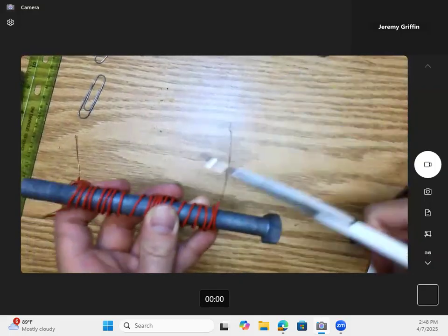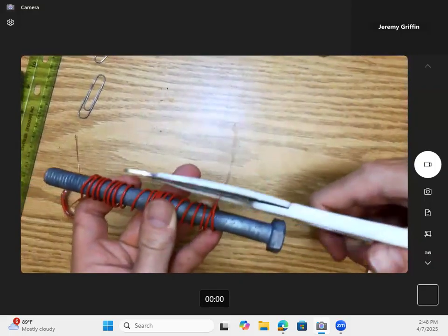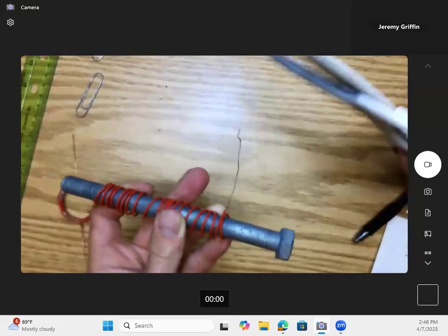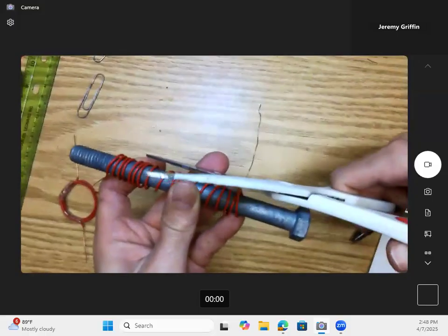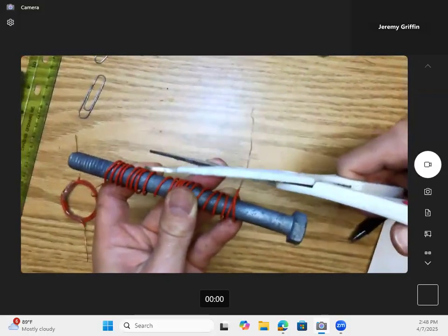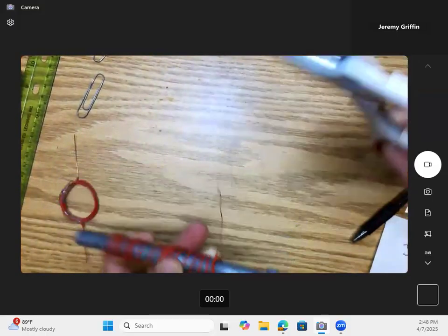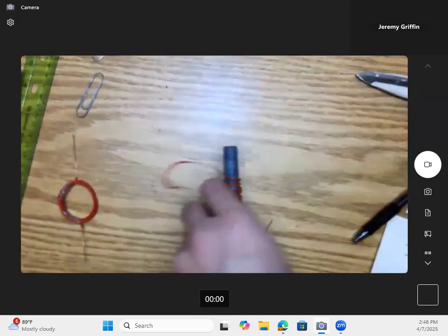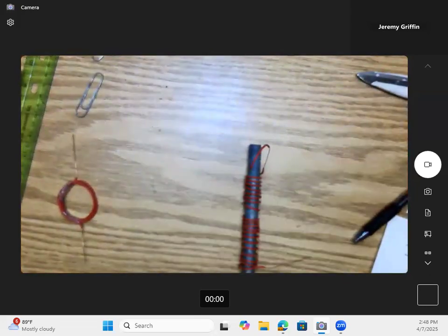Because I've seen students try to do this so many times in the past. It's like, yeah, okay, I gotta strip this wire. Kind of like, bam, bam, bam. That's really, really dangerous for this reason. There's a lot of resistance here, and then you don't know when it's gonna snap, and then it snaps, and you got these big heavy blades, and all your friends' eyeballs nearby, and that is a bad combination.